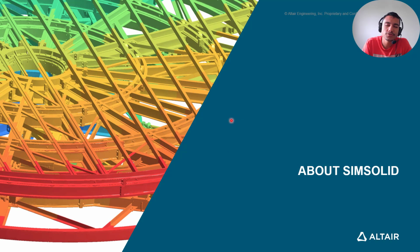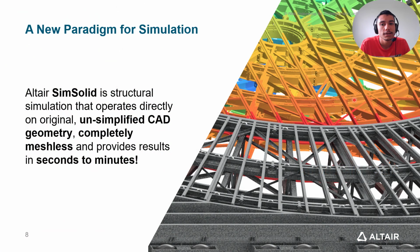Now I'd like to briefly introduce SimSolid in case you have never heard about it. SimSolid is a structural simulation tool that operates directly on the original and unsimplified CAD geometry. This tool uses a completely meshless method with this unique adaptive solution, where the problem will be solved in a number of passes in order to achieve the solution convergence. And this method gives SimSolid both the speed and the accuracy.